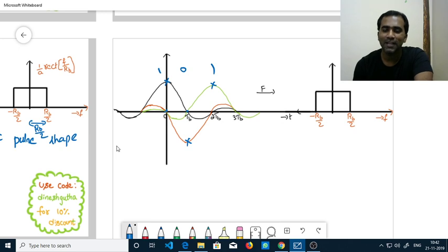That's why it looks like there is ISI, intersymbol interference. Before transmitting through channel itself, it looks like intersymbol interference is there, but it is not exactly there. At the points where we are interested to sample the signal and decide the bits, intersymbol interference is not there. See this one? Here we are going to get only this sample, let's say 5. 5 plus 0 plus 0, it will be 5 only. -5 plus 0 plus 0, it will be -5 only.